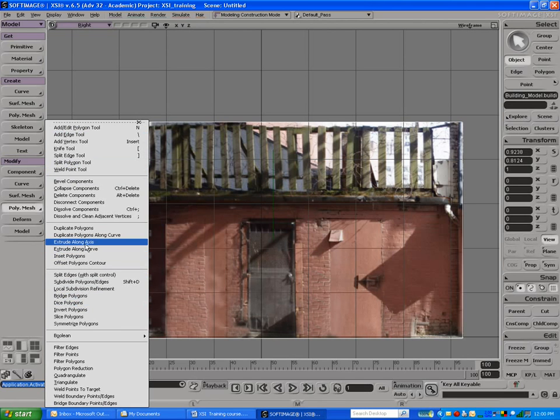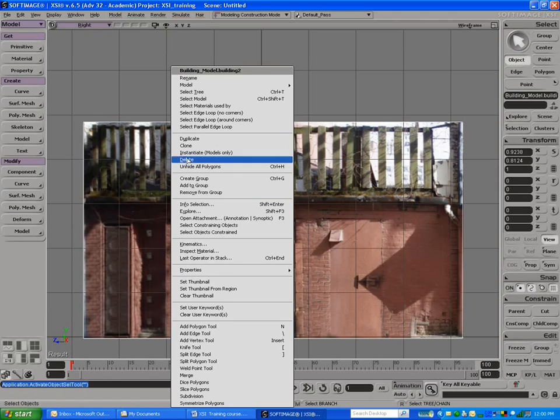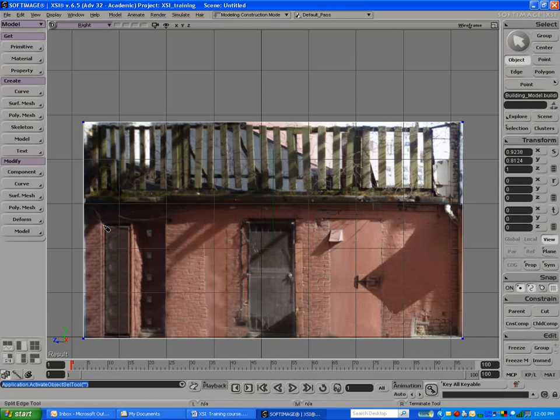There's two ways to access this tool. You can either duplicate a face that will extrude it, or you can use this tool here. Okay. So let's start by using split edge tool. There's a hotkey here. The other way is of course right mouse button or alt right mouse button. You can access all those tools, and you can here see split edge. But you can see the hotkey for that is the right square bracket, and we're just going to go here, and you can see left mouse will split the edge, but middle mouse will do a parallel edge split.